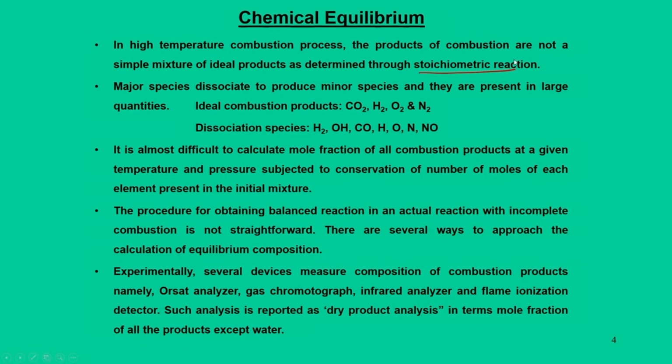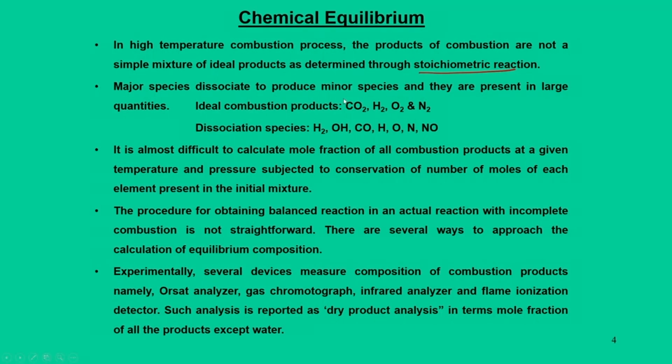That means, what is the exact amount of oxidizer requirement per 1 unit of fuel. That we have dealt with, and we call this a stoichiometric condition. Now, if the reactions are not in the stoichiometric situation, and in fact that is the majority of the cases, then combustion species will appear. There are two types of species, one is major species, other is minor species. And the control of major and minor species is mainly governed by whether the fuel is lean or rich.